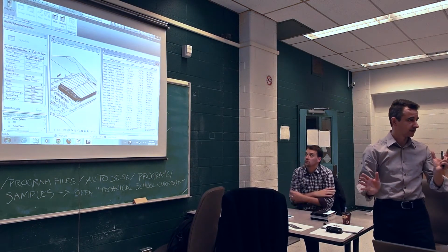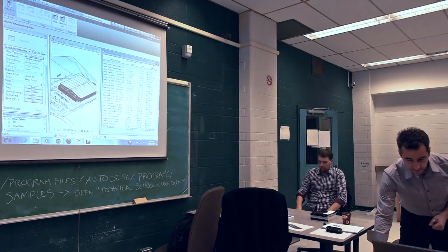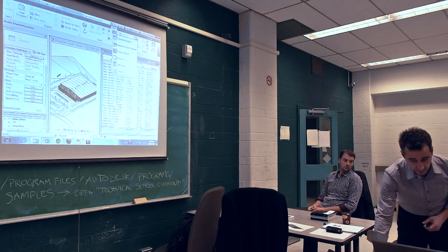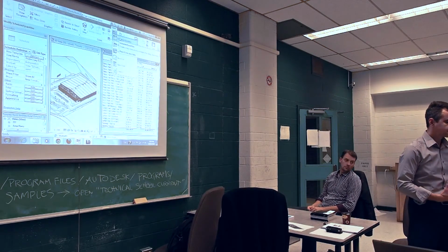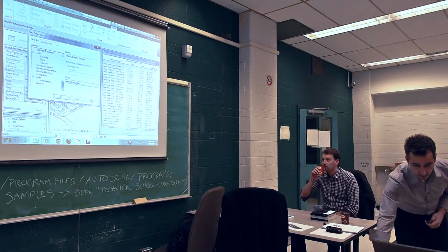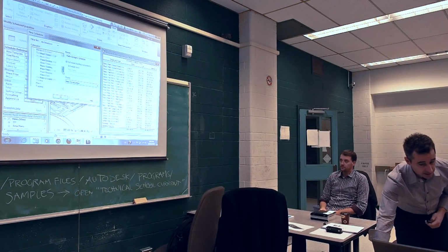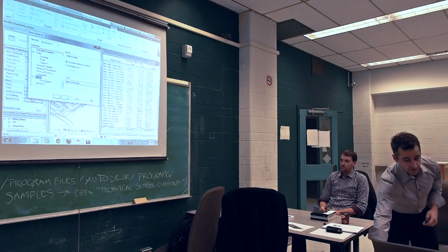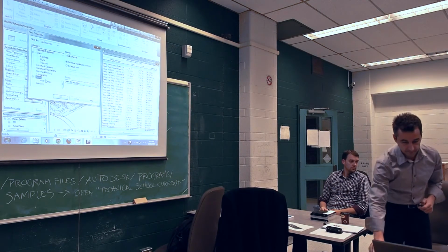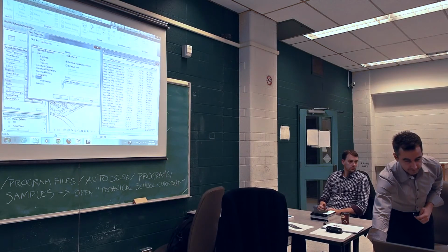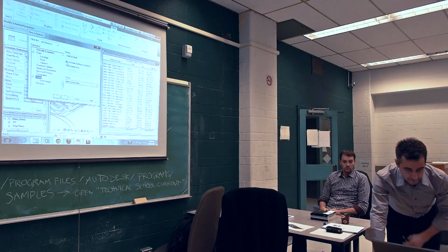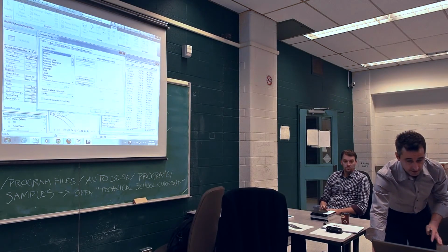How do we get here? Because that's the question. It's all good. Let's go on the View menu, and then in the schedules we have Schedule Quantities. Let's just choose that option. So we'll schedule walls. In the category, this is when we use what to schedule. Let's call it wall schedule, although we know it's a preliminary wall schedule. We schedule building component, that's a default, and we're going to leave that there. This one here. And we hit OK, and we are in known territory now.